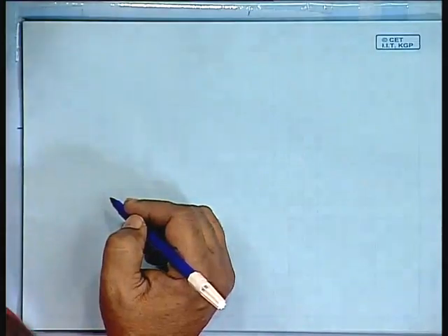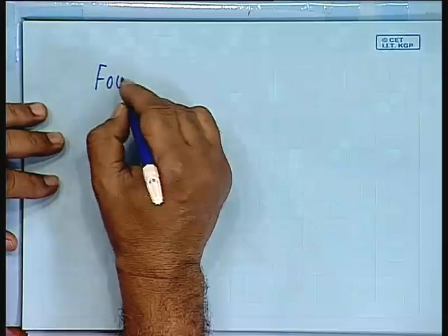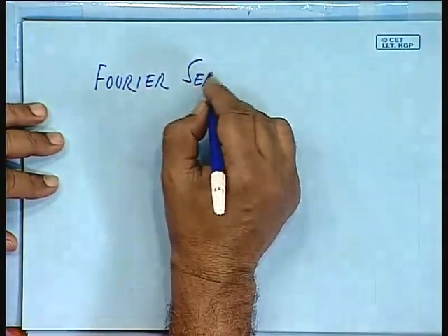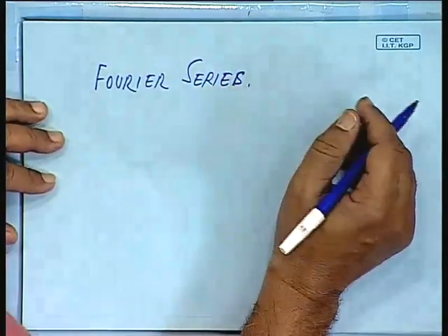Now, in the normal FIR filter design, what we did, we took the Fourier series, and then truncated it at the desired length. It can be proved, it is there in all the textbooks, that if you take the Fourier series coefficients up to any desired length, then that will be the best possible combination of coefficients which will give you the minimum error.